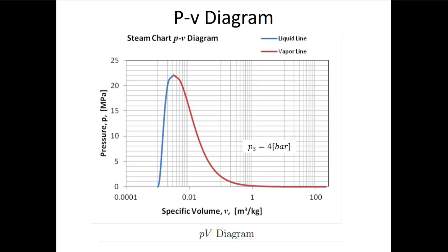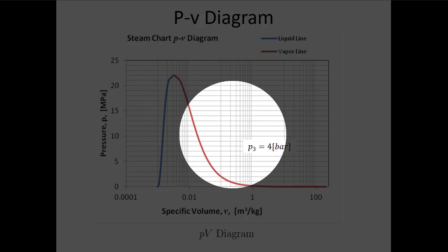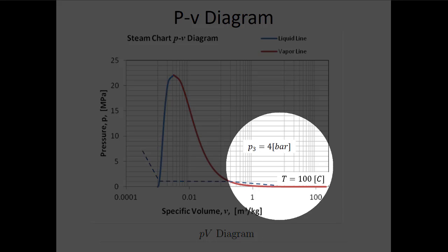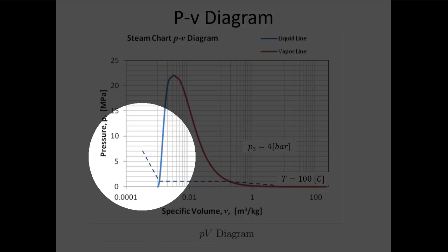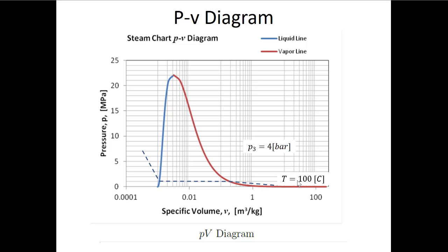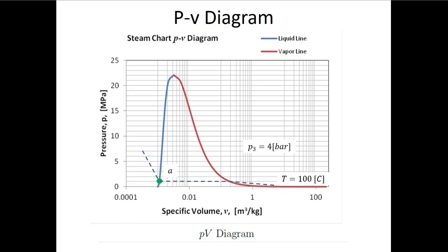The PV diagrams, for me, I find they're a little bit trickier, right? Because the constant temperature lines here are going to slope down as we go from left to right, right? So here, I know that initially I'm talking about 1 atmosphere, right? And here, just for context, I'm drawing this 100-degree line here, right? So this would be saturated liquid at 100 degrees.